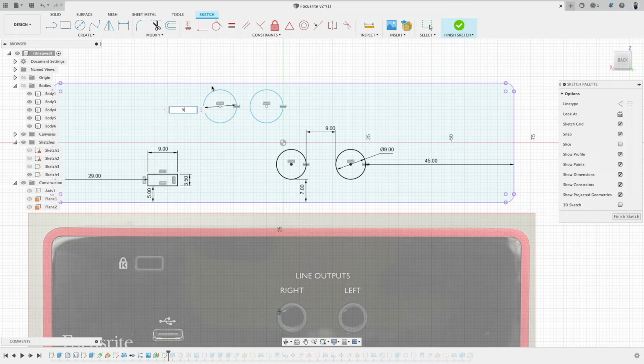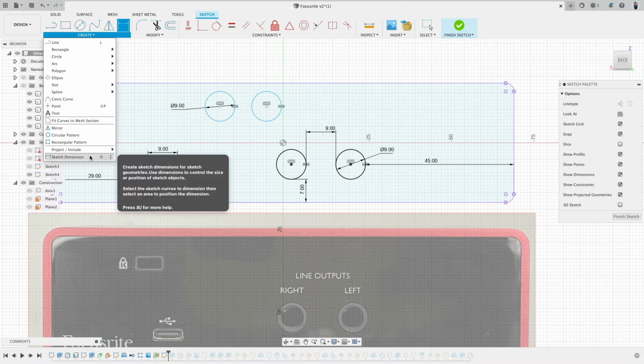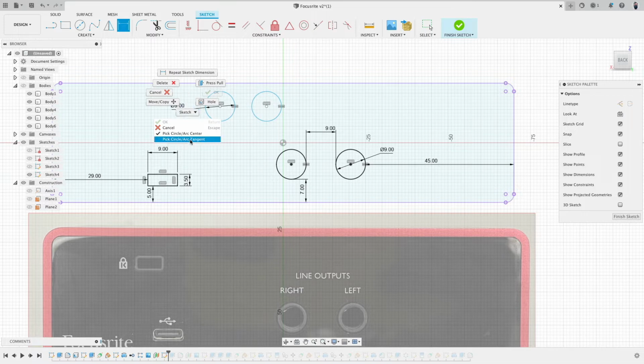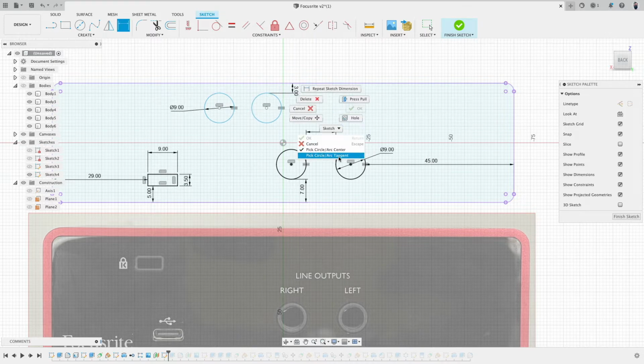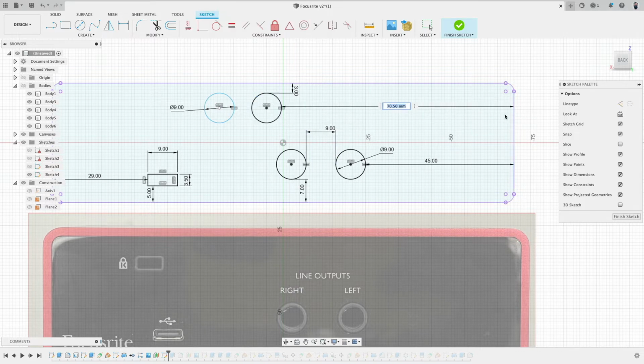Very good. And now if I would like this ring to have a distance to the top of 4 millimeter, I can go to dimension, right click, say tangent, and this is the important thing. So tangentially make me a dimension 3 millimeters, and then right click, because it switches back to center, there to here, maybe by 50. Yeah. And then also the distance between them, again tangent, so right click with the mouse, 10.